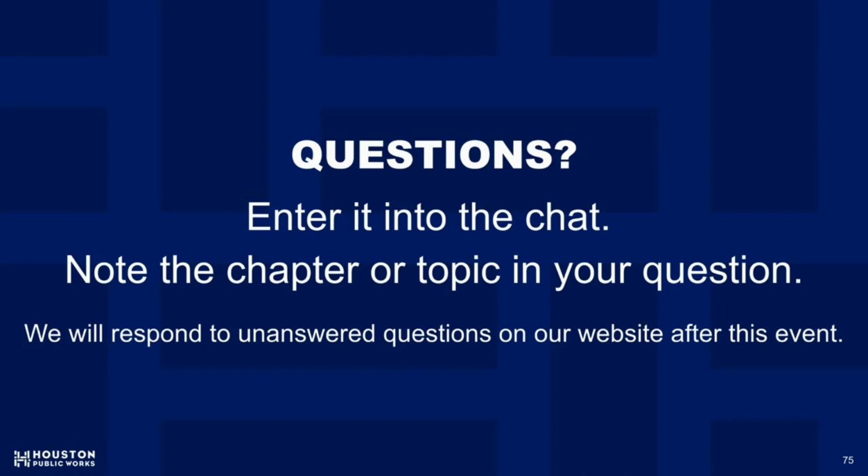One more question we'll ask before we move on. Will 13-hour TMCs be required at all study intersections or only major intersections? They're intended to be collected. There are no additional requirements for turning movement counts. This is just where turning movement counts were previously already required. We are now just requiring them to be 13-hour instead of just peak hour. So we're not expanding the scope or number of places where a turning movement count would be required.